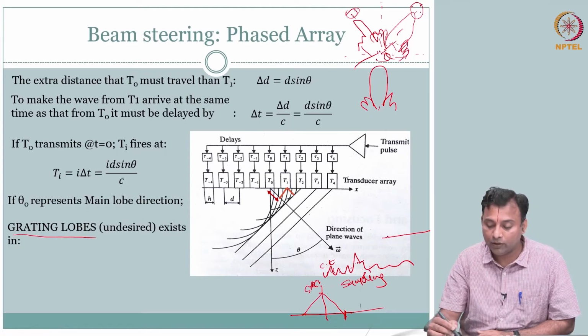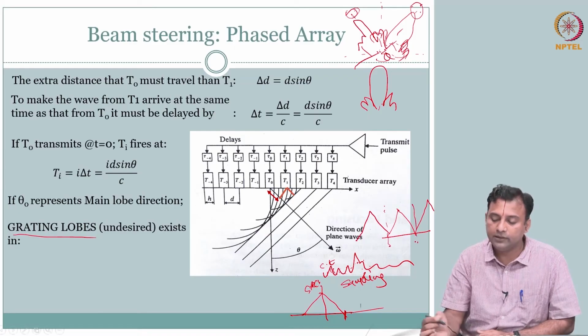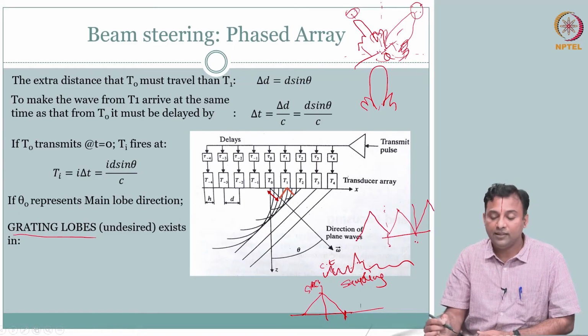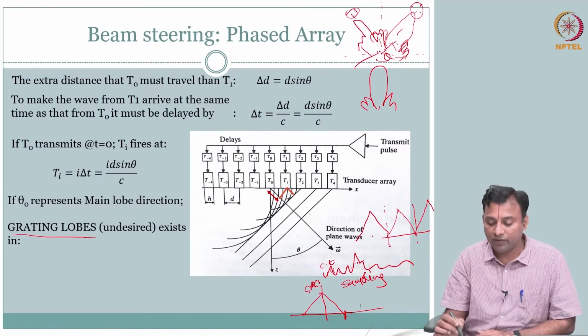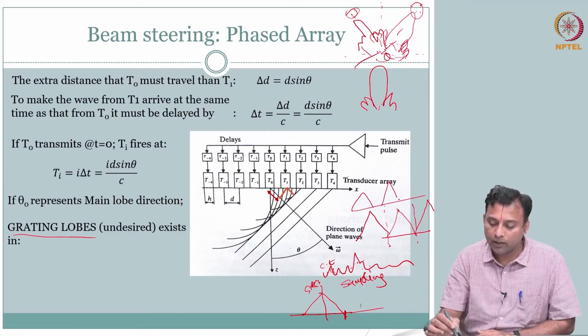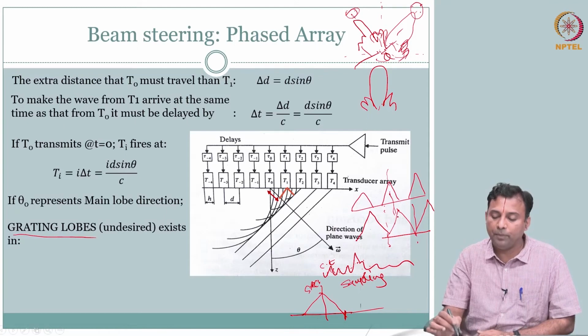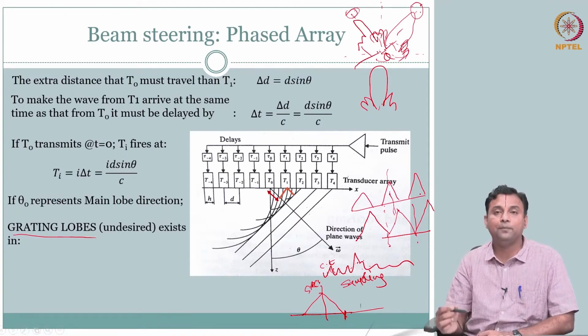Your spectra is going to be like this, right? This is at Nyquist. If you sample much higher than the Nyquist, there will be separation, right? You can have 1.5. So essentially you have copies of your spectra.